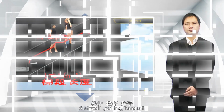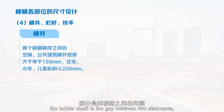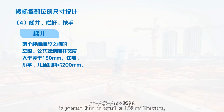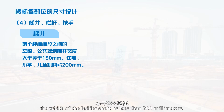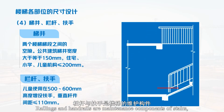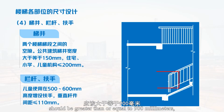Stairwell, railing, handrail. The stairwell is the gap between two staircases. The width of the stairwell in public buildings is greater than or equal to 150 millimeters. In residential buildings, primary schools and children's institutions, the width of the stairwell is less than 200 millimeters. Railings and handrails are protective components of stairs. The height of indoor handrails should be greater than or equal to 900 millimeters.